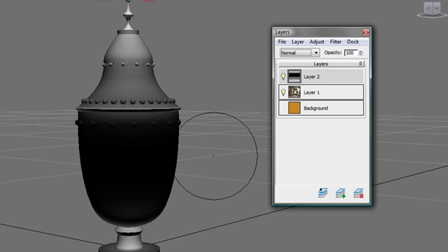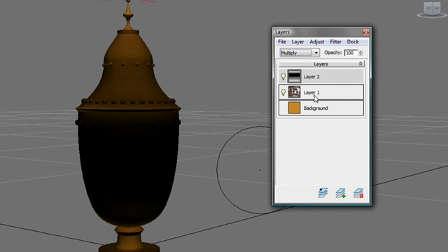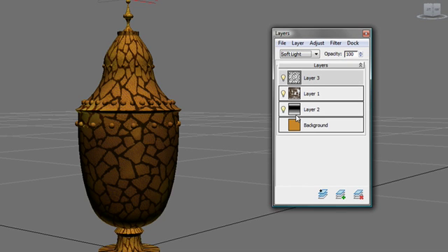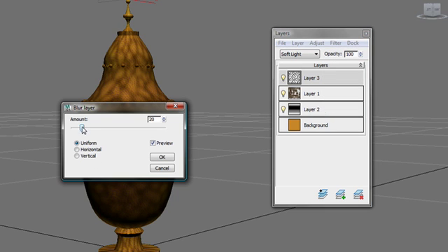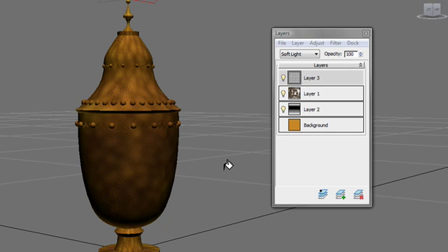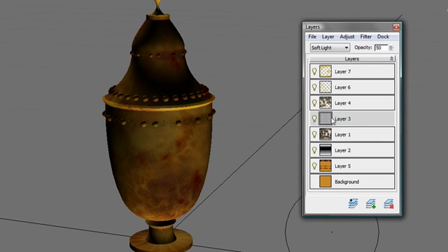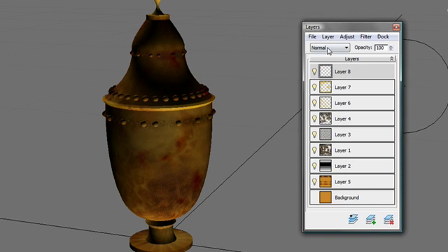Here, I am loading a previously calculated surface map that I can multiply on top of what I have already painted. I can also decide to fill the object completely with the selected pattern. I have options to filter my layers such as blur, sharpen, find edge, distort, and more. Very similar to the Photoshop workflow, Viewport Canvas painting is flexible and the capabilities are infinite, allowing for creativity.